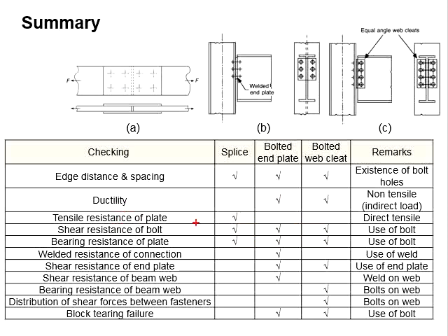Again, when you have bolts, there will be bolt holes, and when you have bolt holes, under load, there will be bearing resistance of the bolt hole. Therefore, all three of the connections will have to check for the bearing resistance of the bolt hole.